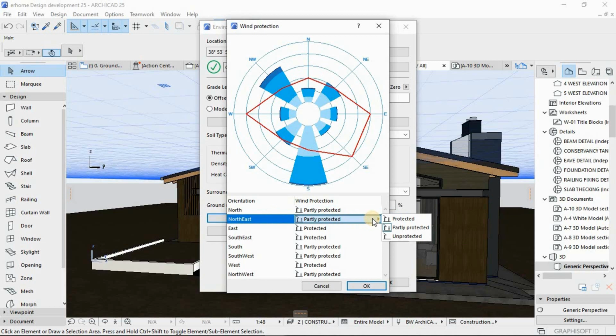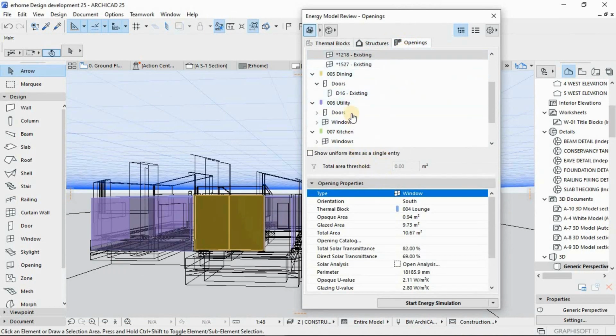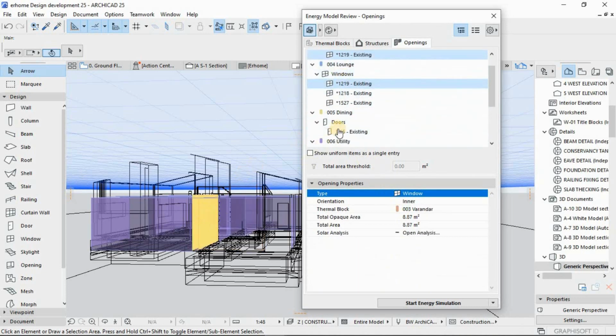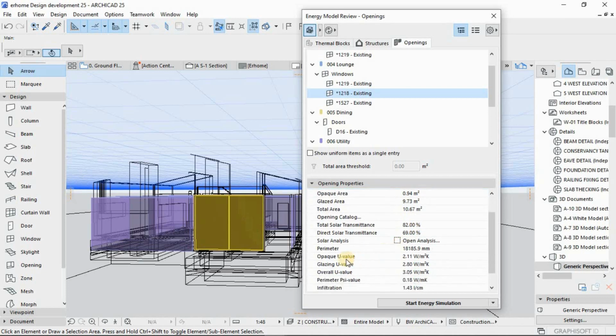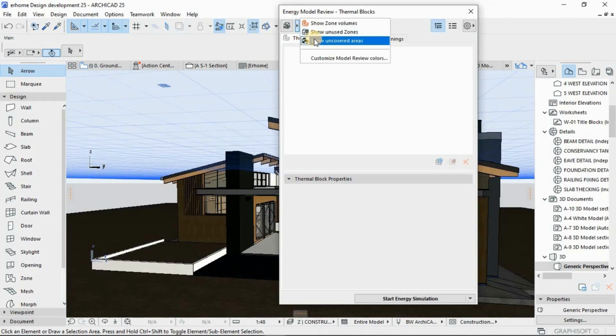I'll leave the link in the description. I think we have made 2-3 videos about Eco Designer. With energy modeling, you will be able to have an estimate of the total energy consumption of a building and assess its potential energy savings. And ArchiCAD offers various energy evaluation functionalities out of the box, while providing various project export possibilities for other applications, including PHPP, the MSBIM energy model, VIP-Energy, and so on, as well as a dedicated Green IFC translator.